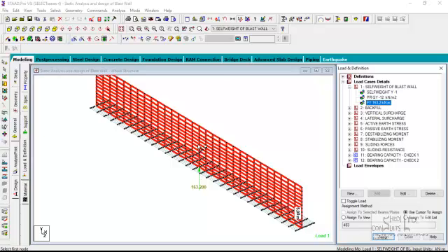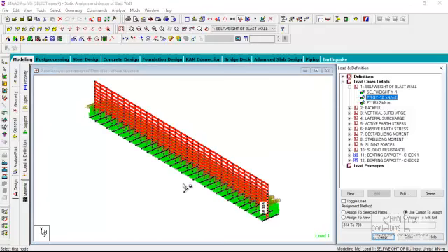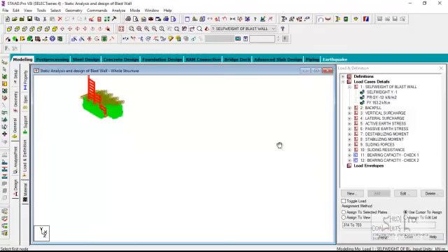It counters it and gives you the total weight, assuming that you modeled a 4 meter height of wall. So the weight corresponding to 34 by the thickness of the wall by 0.5 was applied as a counterweight, so that the equivalent total weight will be the total weight of the wall, assuming a height of 4 meters. So that was done. And then you have the weight of the foundation base. Okay, that's the first loading.